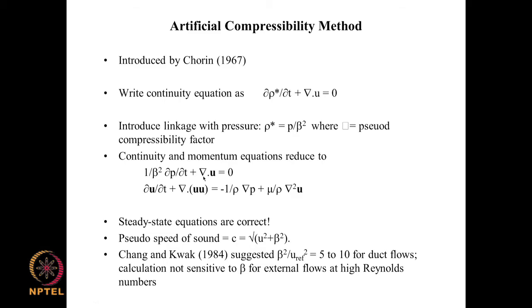And these equations can be used for 3-dimensional flows, because we have written them here in the vector form, and this del dot u will become equal to dou u by dou x plus dou v by dou y plus dou w by dou z, and here you will have 3 equations, x momentum, y momentum, z momentum equation, in which the same pressure which is coming out of this equation is used. So, there is no difficulty in extending this to 3-dimensional flows.